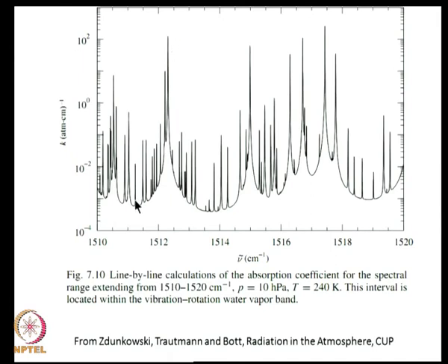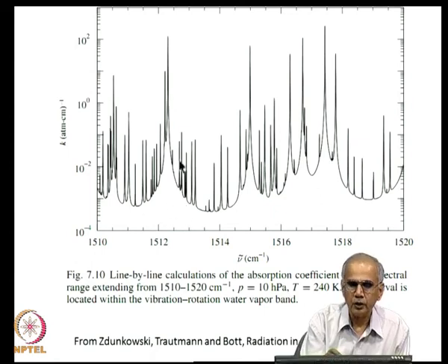and hence you can see that when you do those integrals for radiation calculation, one needs an extremely high resolution in the wave number axis to be able to really capture these peaks, because if you use a very crude step size here, you will not capture these peaks.